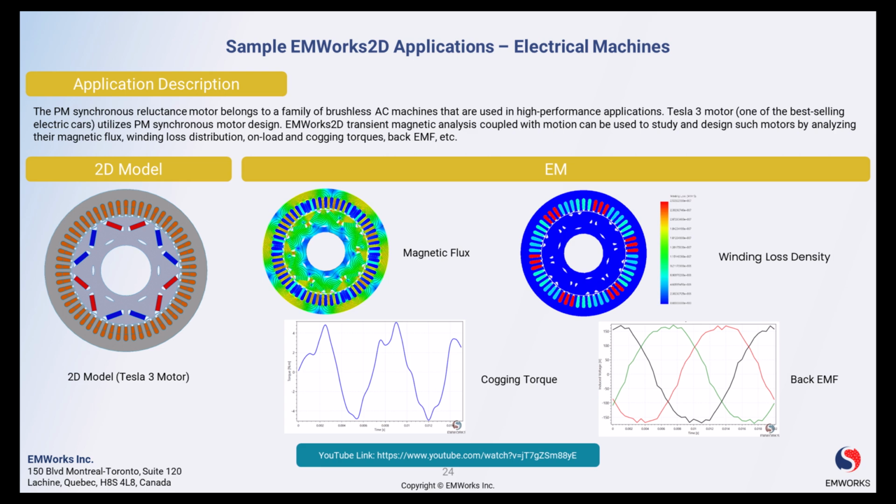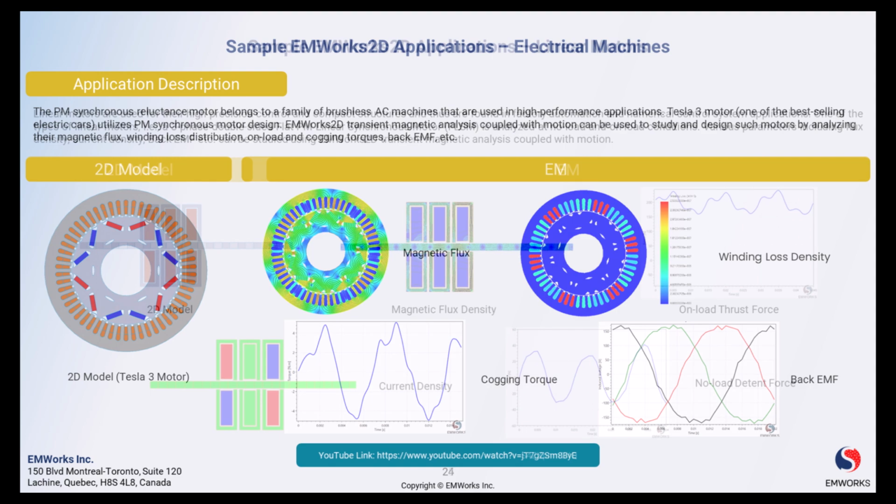The 2D electromagnetic field simulation provided in-depth characterization of torque production, losses, vibrations, demagnetization withstand, and other parameters across the operating speed range. The insights from the virtual simulation helped engineers refine the electromagnetic design and structural parameters to improve torque density, efficiency, reliability, and control.